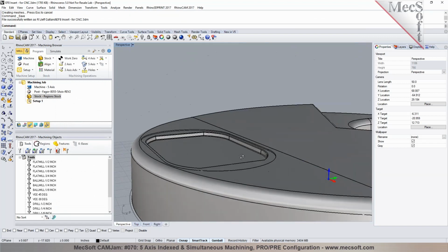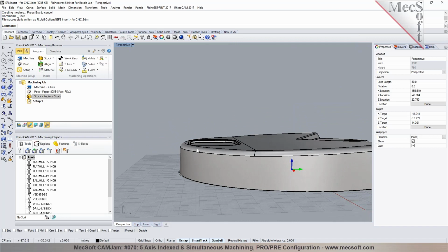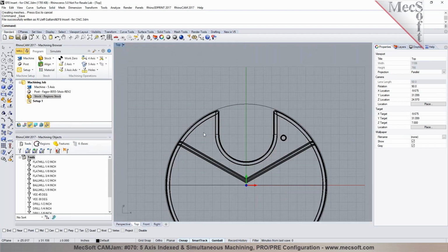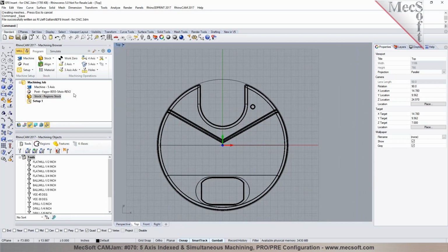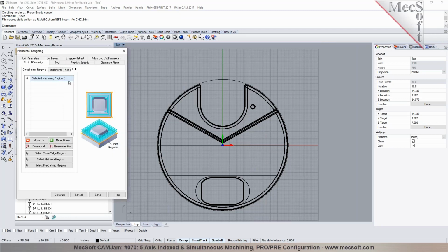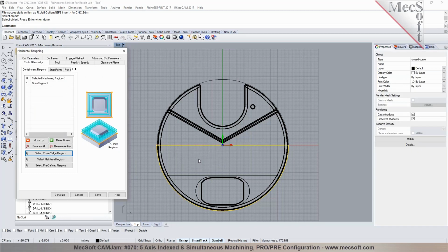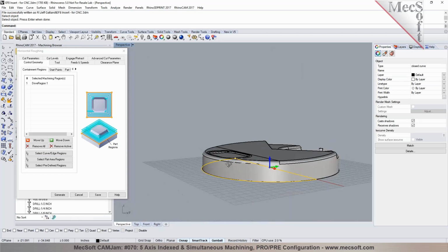Would there be any questions so far, sir? Good. Okay, now you see that there's a draft in here, right, on the top of the surface in here, and we only wanted to do 1/2 of it. So what we could do first is start with the roughing process. We could do for the top areas, we could just do a roughing. So we could use 3-axis, and we can start with the roughing process in here. And for containing or constraining the toolpath, I can just pick this boundary curve that you created already. I can use that as my boundary curve to contain it.